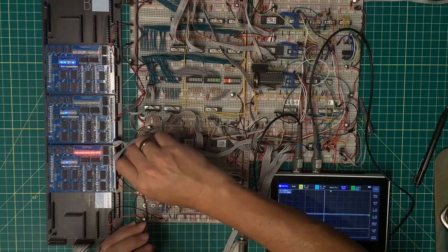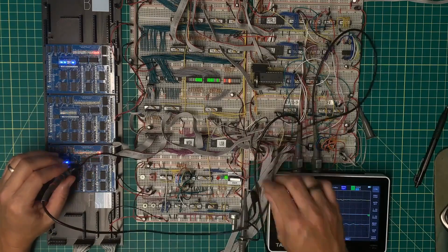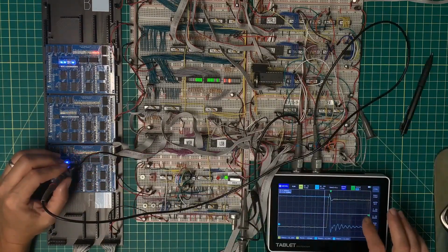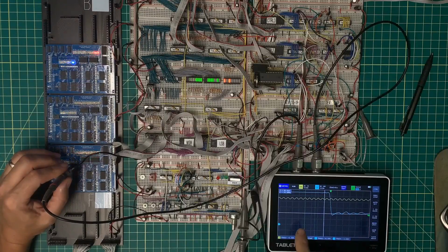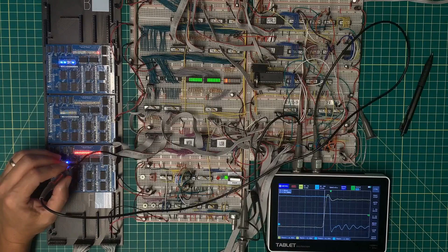The blue trace I'm going to drop into what would be my main bus assert signal on R2 over here. And zooming in just a little bit here, without actually getting in and measuring it, the delay looks like it's about 50 nanoseconds, give or take. And the shape of those signals looks really pretty good. So I'm not horribly concerned with that.